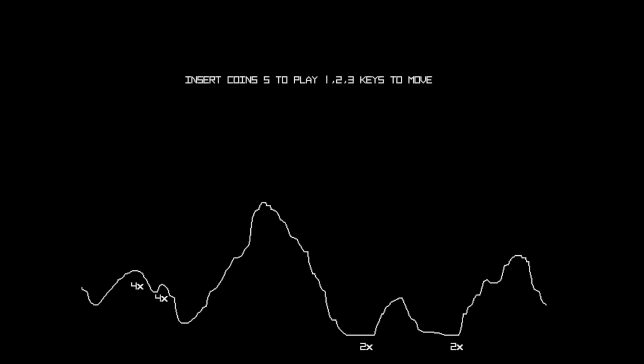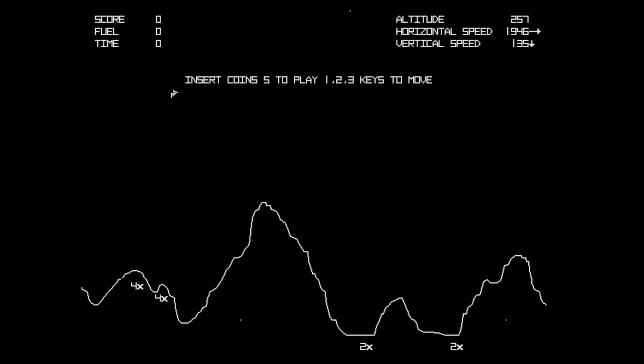As it initializes, there are some debug messages coming up on the terminal emulator, but once those have done, we should see the 2-color 640 by 480 graphics appear to be working there. There is a little bit of snow, which we're going to look at in some future videos to sort out the timing between the CPU accessing the video RAM and the video card accessing the RAM.